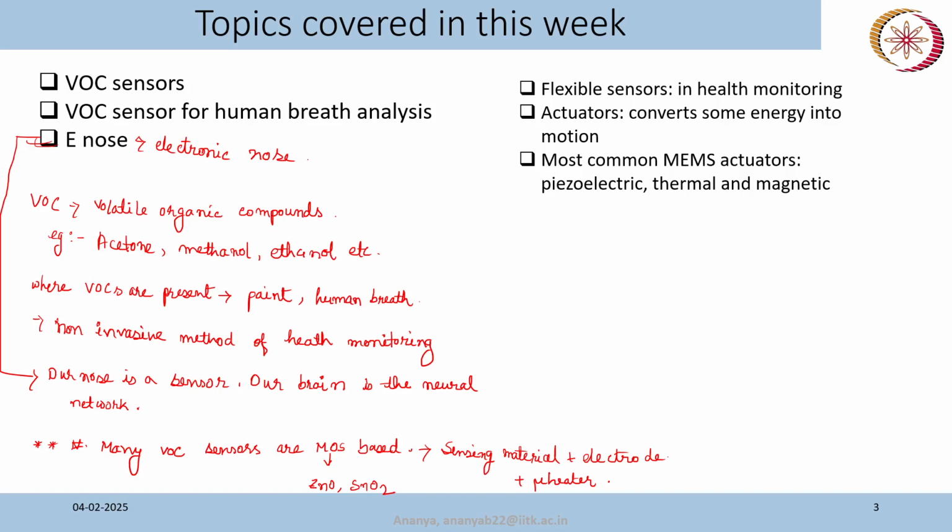On top of the insulating layer you will make your sensor, a sensing material plus electrode, and depending on how you design the sensor, you will measure the resistance or the voltage across the sensing material using the electrode configuration.